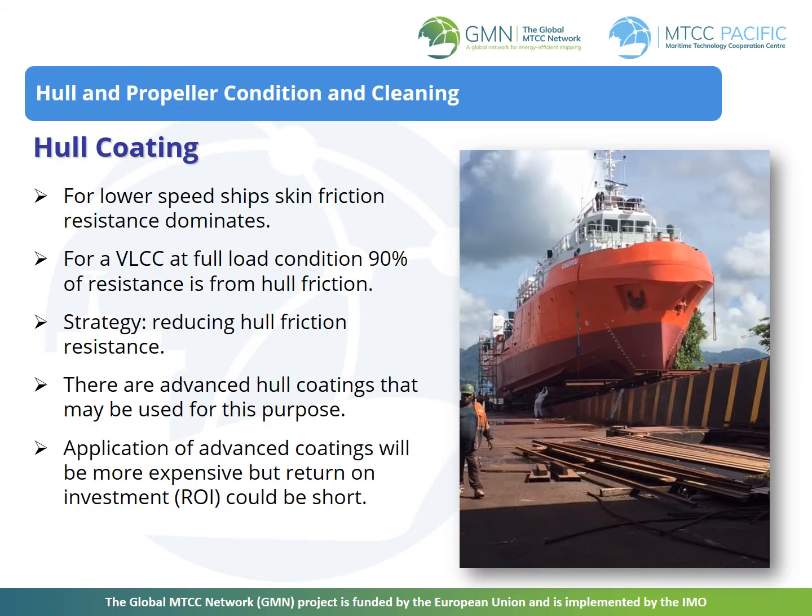The hull of vessels in a fleet is coated with anti-fouling system. In general, the smoother the outer hull is, the less will be the resistance, and therefore the vessel efficiency is improved. The effectiveness of hull coating systems would therefore largely depend on the level of maintenance and cleaning undertaken. Vessels in a fleet can be considered for application of self-polished coatings if this is not already occurring.